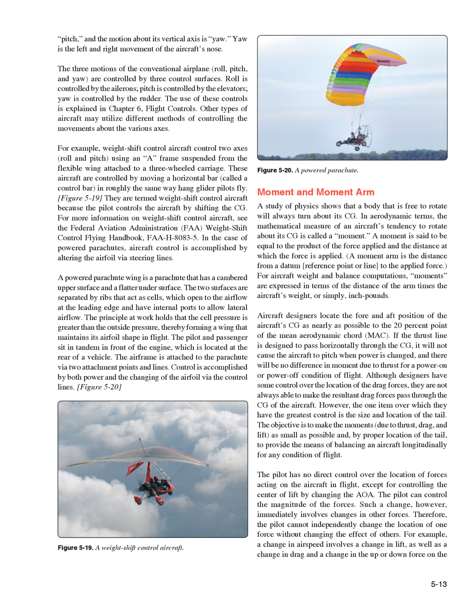A study of physics shows that a body that is free to rotate will always turn about its CG. In aerodynamic terms, the mathematical measure of an aircraft's tendency to rotate about its CG is called a moment. A moment is said to be equal to the product of the force applied and the distance at which the force is applied. A moment arm is the distance from a datum, reference point or line, to the applied force.